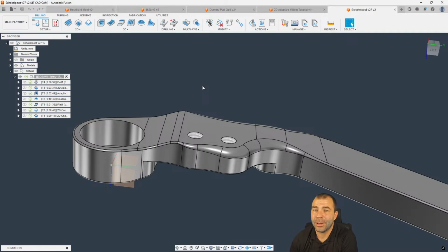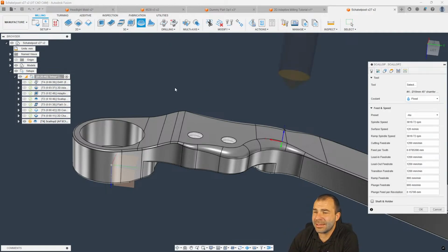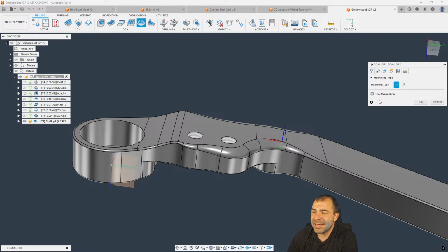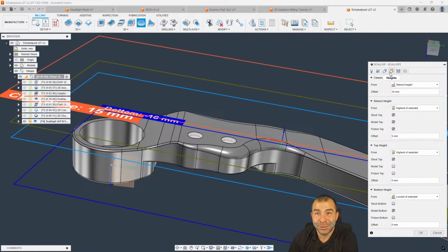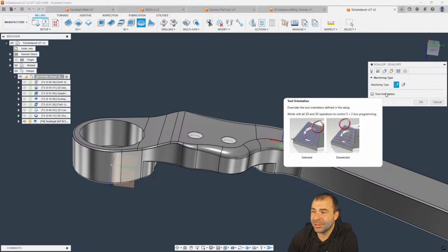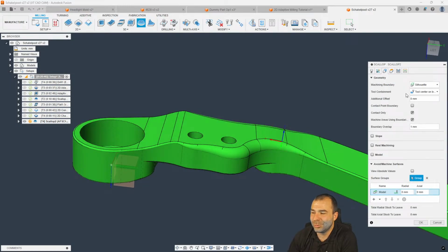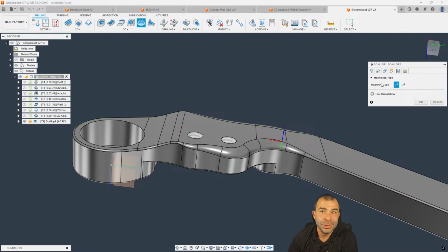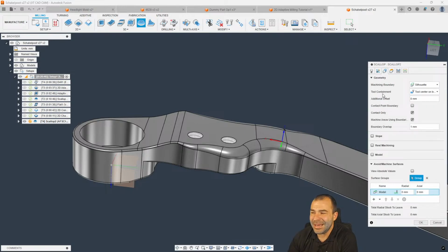And I don't see it that way, because if that was the case in a toolpath, as we've seen Autodesk recently do, they put everything in an order of operations, right? So the idea is now you actually select multi-axis. So if you've ever called me on my phone for support, when I try to walk you through things, hey, I need something in the heights tab, it is no longer the 3rd tab, right? It's now the 4th tab. But the idea is that when you turn on certain things here, it actually causes other things to happen later in your toolpath. If you're like me, you rush through, you do all this stuff here, and then you realize, oh no, I need to do tool orientation. It's the same concept with the geometry tab. It's the same concept with the passes tab.